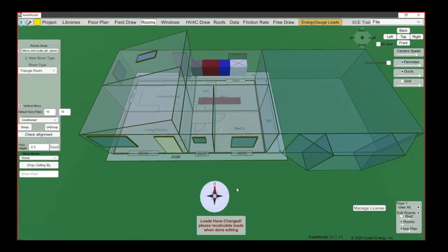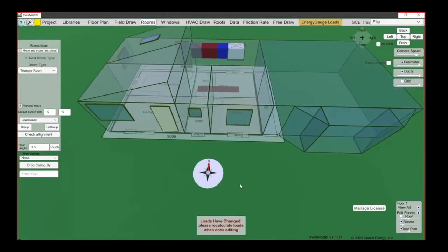I used to teach a 3-day Manual J class. In fact, I used to teach it down at Steve's place in Tulare there at the Southern California Edison Training Center in Tulare. We had a 3-day active Manual J, S and D class, and one of the example houses, if I remember right, is about a 2,500 square foot house, and when it was facing one direction, it was a 2.5 ton air conditioner, and when you rotated it 90 degrees, you take the exact same house and you rotate it 90 degrees, it went to a 4-ton air conditioner just because of the rotation.